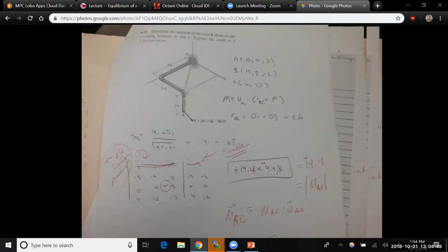The unit vector is 0.85i plus 0.6j, but you don't put i, j, k across that. You just do the determinant of the unit vector, which is on the first row, the position vector, which is on the second row, and the force vector, which is on the third row. That gives you a scalar, not a vector. About 3 or 4 people were doing that. That scalar is the magnitude.